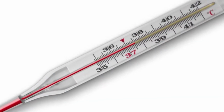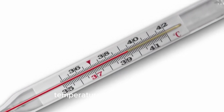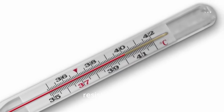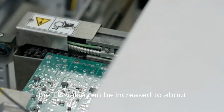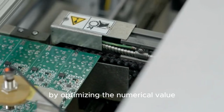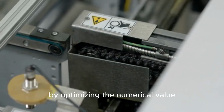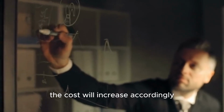First of all, the Tg value, the glass transition temperature, can be commonly understood as the temperature resistance level. At present, the ordinary FR4 board is generally 140 degrees. If the user's needs exceed this range, the Tg value can be increased to about 160 to 180 degrees by optimizing the resin formula and other processes. Of course, the cost will increase accordingly.